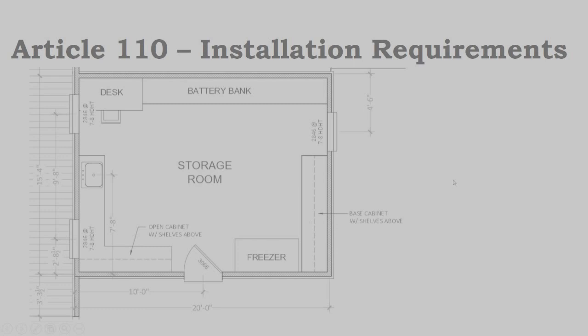And where these requirements get tricky is especially when you're involving battery banks. Because if you're doing, say, an off-grid residential home, you're likely working with lithium-ion battery banks, and these things are huge. I have such a home at one of my project sites, and this is how the architect sketched up the room inside the garage. That's going to be an air-conditioned space where we're putting our inverter equipment and our battery bank.